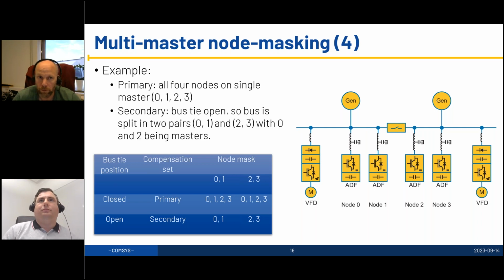So it means that if you have a motor that acts as a load and the motor is spinning and you have a short circuit, then even when the voltage goes to zero, of course, the motor will keep spinning and it will feed power to the grid. And you use this rule of thumb that 6 or 7 times the nominal current is actually a contribution to the fault current. And those currents can be very significant.